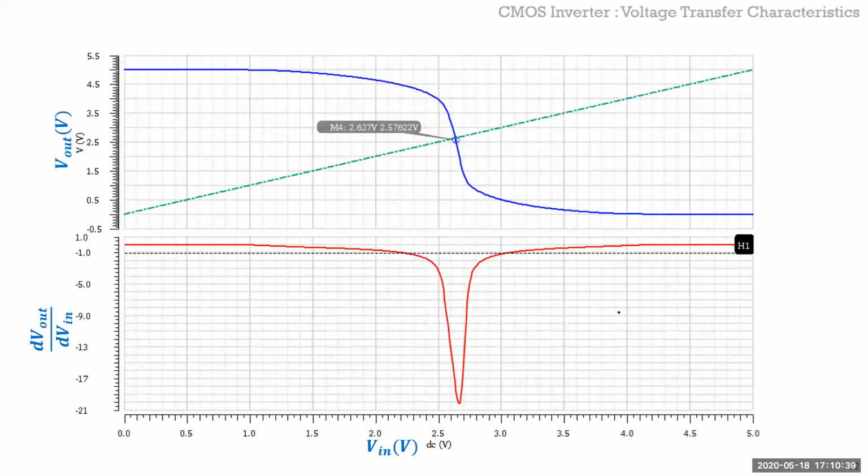So that's the definition of it. And I'm just showing you the transfer curve again. When the input voltage is 0, you start with output voltage at VDD, and this remains like that till your input voltage reaches VTN. Once it goes above VTN, the NMOS turns on. The NMOS is in saturation, the PMOS is in linear, and there's a middle region where both are in saturation. I'll show a diagram with a little more detail.